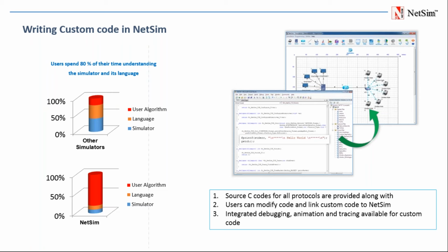So considering these difficulties, NetSim has been designed with its GUI feature along with custom code editing, where we can design and analyze our network in the GUI, and if we wish to change an existing protocol or create our new protocol, that can be done using Microsoft Visual Studio 2010 version, where we can save our files in DLL extension, and further we can link it with NetSim GUI. So that is the main difference between open source tools and this NetSim software.